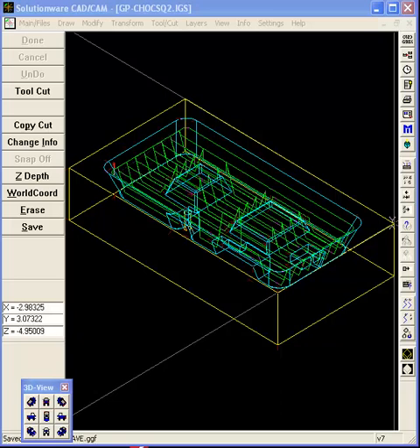One thing about this particular cut kind is that it won't recut sections of the surface. As it roughs to one depth, when it comes to get the next deeper depth, it will wrap up and over the section that it had previously cut. So it won't be recutting a lot of the material.